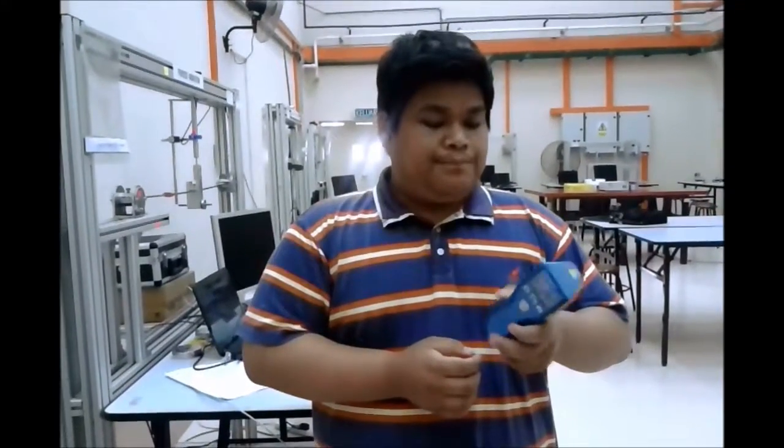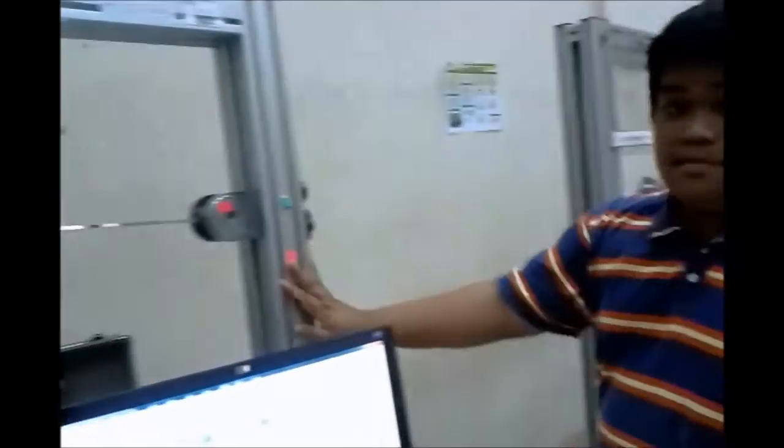And there are also tachometers that record in experiments and also in the real world outside, in industry. Okay. Next, I will present the procedure and how to use the tachometer. This is an operating tachometer in this vibration lab. This is a functional tachometer that will record the RPM, RPS of this gear and shaft of this experiment.